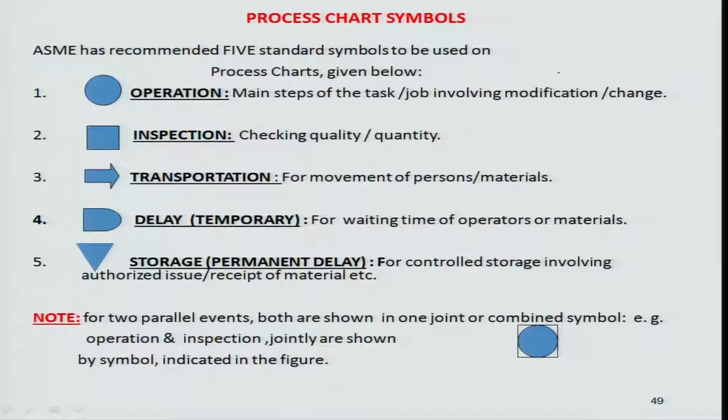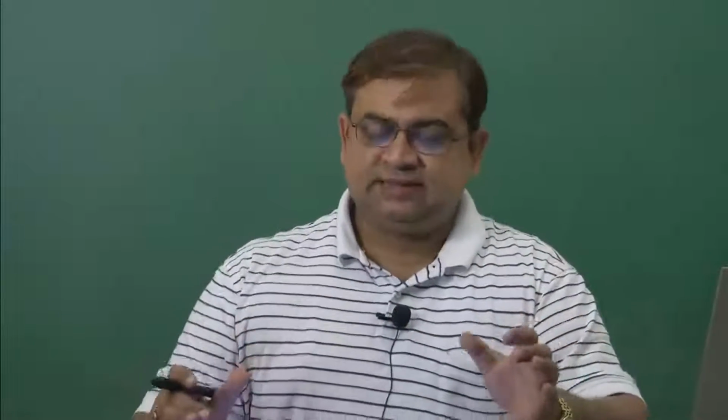Once you have identified a job or a process through a Pareto chart or some other mechanism, through which you have the top 20% of causes of delays or wastage of a system, the question is that you look at such a task or process to perform the motion and time study to make it more optimized, and look at everything in terms of good representation or recording of the different facts associated with the motions and the time scales in such tasks.